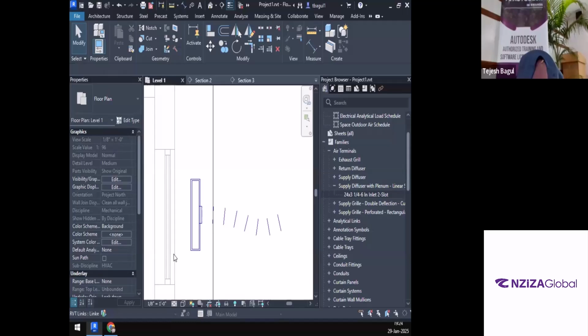Okay. We were talking about the external static pressure yesterday, right? So when we were talking about rigid duct for calculation of the static pressure, we were looking at 0.08 inches per 100 foot. So if you have a 100 foot length duct, only 0.08 inch will be dropped in the duct. But over here, for the length of 5 feet only, it might be somewhere like 0.2 inches or 0.3 inches, depending on the number of bends that there are in the duct. Okay. For that reason, always make sure you limit your flex duct to a maximum of 5 foot.